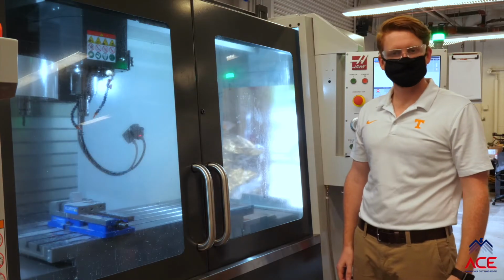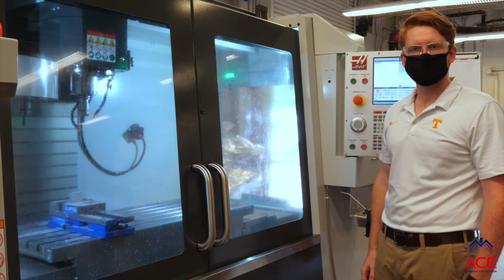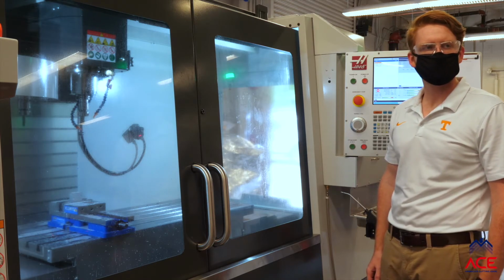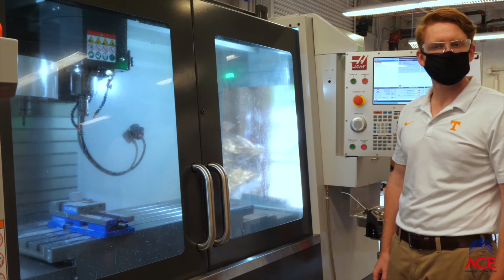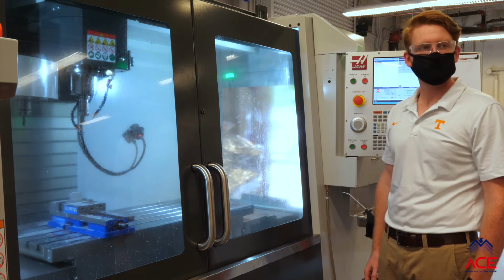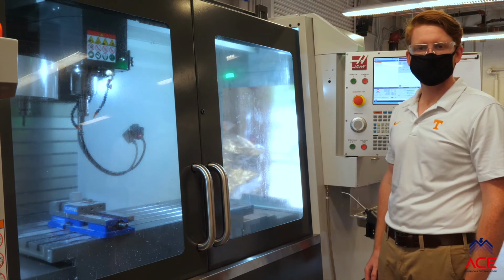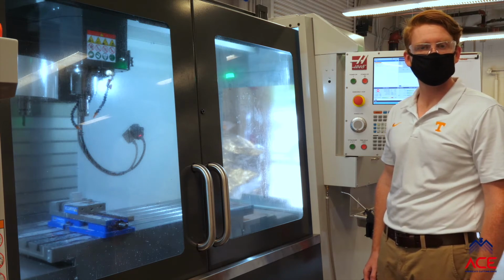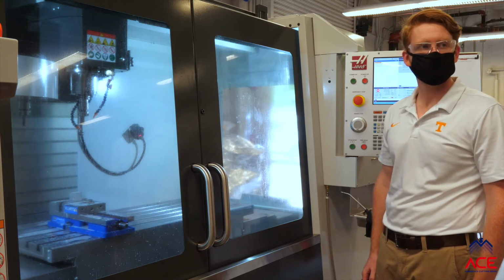So now we're ready to begin our cutting tests. And as I mentioned, we'll do 1 cut for unstable or chatter and 1 cut for stable machining using the parameters that we already identified using our stability map and the MillMax dashboard. So what Greg's going to do is first complete a tool change to move the tool that we already measured into the spindle. He's going to adjust the coolant lines so that we have the coolant pointed at the tool, and then complete our first cutting test, which is the chatter demonstration. Greg?